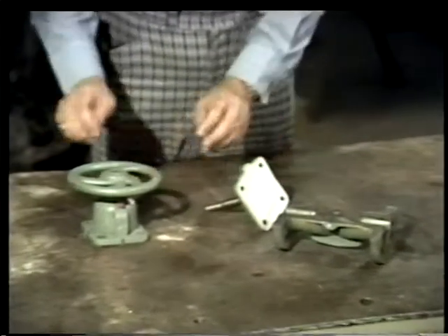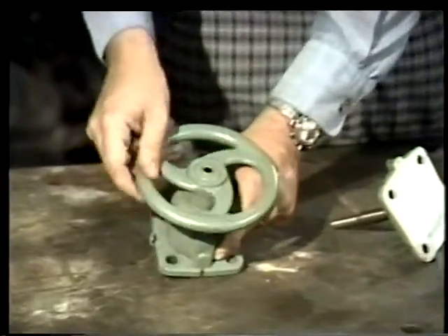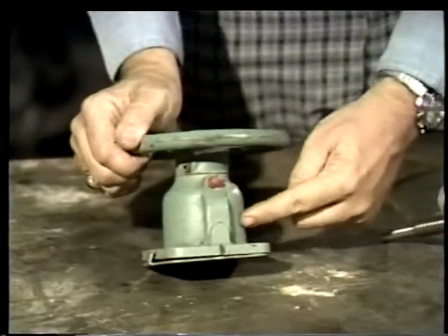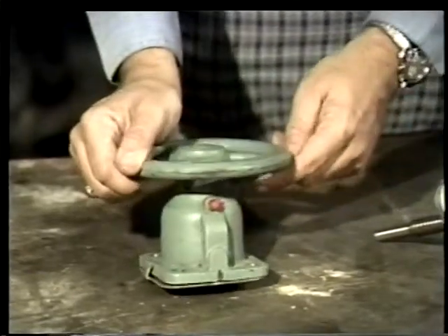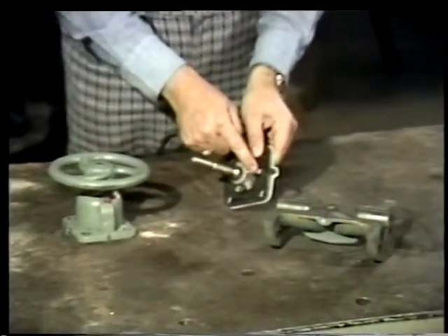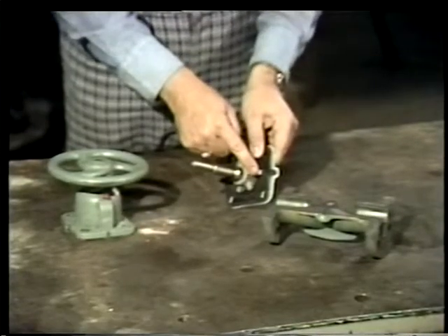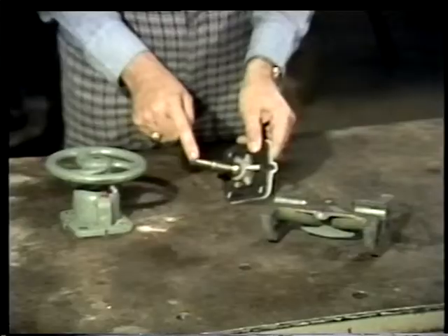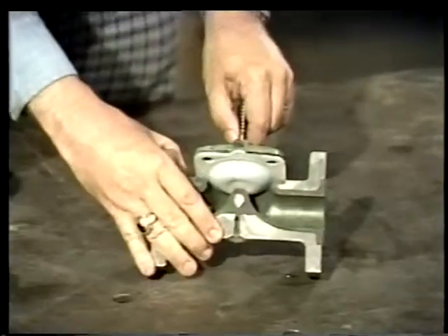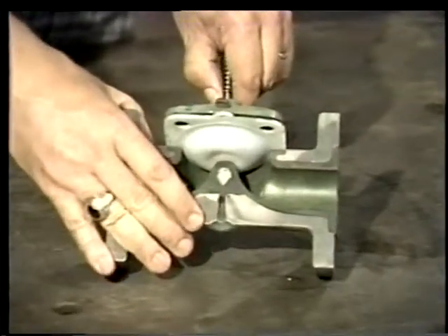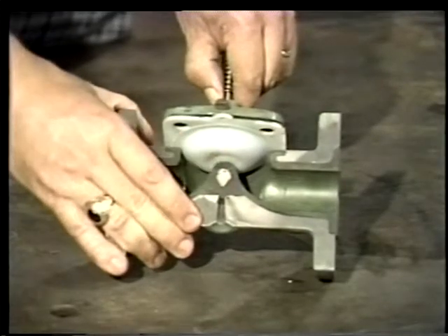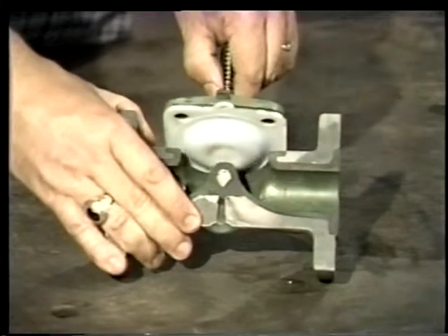Although somewhat different in design, the hand wheel on a diaphragm valve is like those found on a gate or globe valve, and the bonnet is similar to the bonnet on a gate valve. It is large enough to provide a storage area for the compressor when the valve is fully open. On a diaphragm valve, a compressor is connected to the stem, and when the compressor is lowered, it presses against the diaphragm. The diaphragm itself is flexible, and when pressed against the seating surface of the valve, it will stop flow. It gives an excellent seal, even when slurry is carried through the valve.